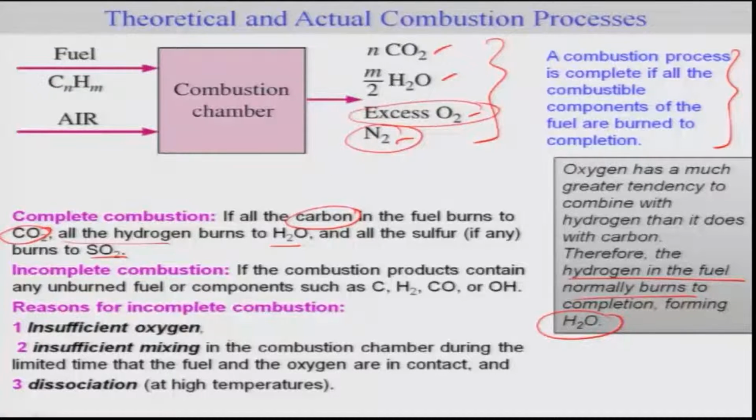Now if there is an incomplete combustion, then the combustion products contain components such as C, H2, CO and OH. So what are the reasons for incomplete combustion? Of course the first is that you don't have sufficient air or sufficient oxidizer, that means insufficient oxygen. Another possibility would be insufficient mixing in the combustion chamber, given the limited time that fuel and oxygen are in contact. If you don't allow fuel and oxygen to have proper contact, that means the time is limited, and hence it doesn't mix well, and then it doesn't burn. So this is another possibility.